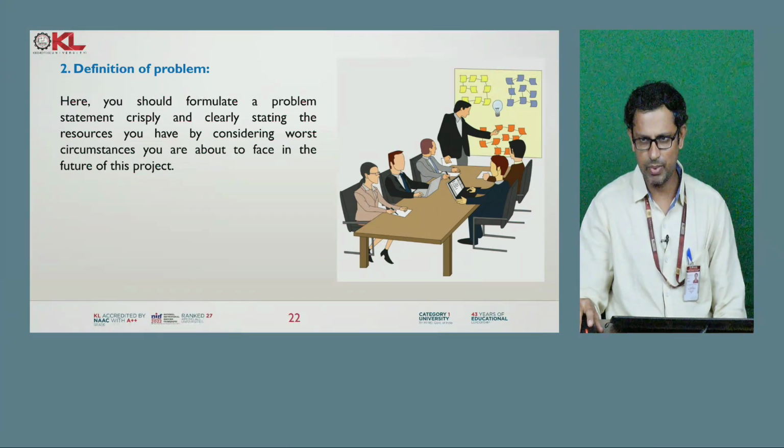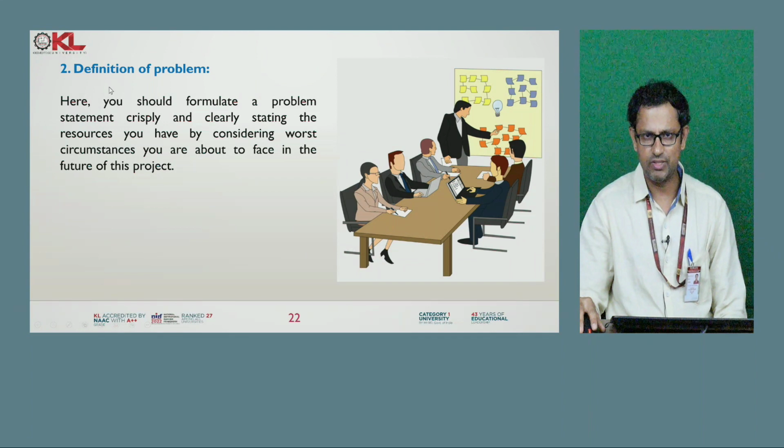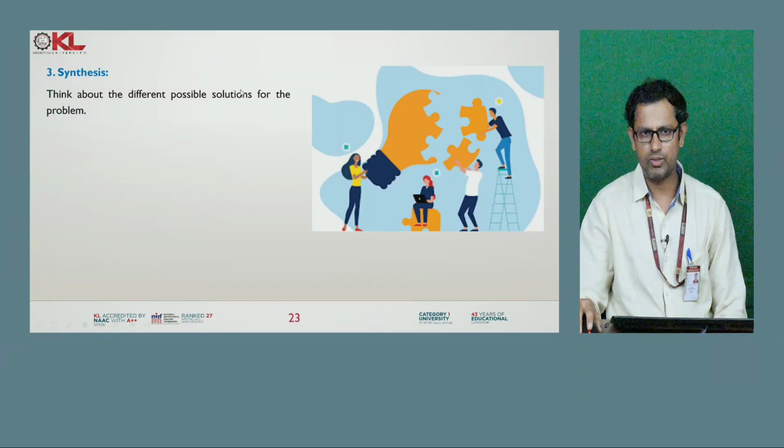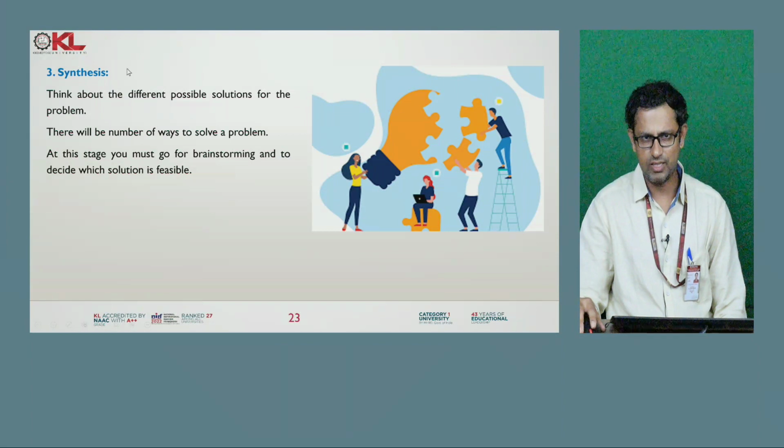That is why the first step is identification of the need of the customer, and the second step is you have to define the problem clearly. Okay? So that is the second step. Then the third step is you have to do the synthesis. In this synthesis step, for the defined problem you have to think of different possible solutions.